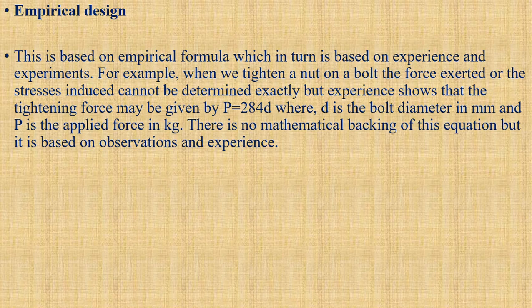on experience and experimentation. For example, when we tighten a nut on a bolt, the force exerted or the stress induced cannot be determined exactly, but experience shows that the tightening force may be given by P = 84D, where D is the bolt diameter in mm and P is the applied force in kg. There is no mathematical backing of this equation, but it is based on observation and experience.